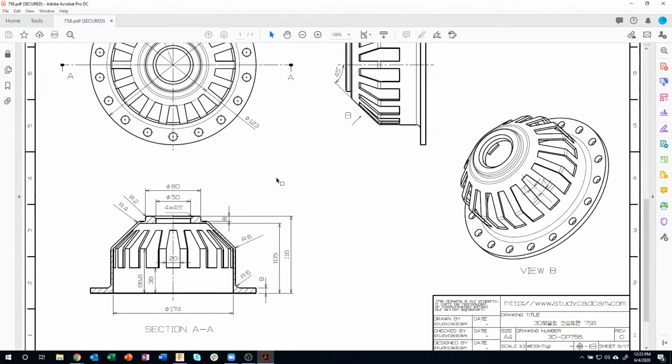Well, there's a couple options here. Now, I'm a little bit nervous because I said I want to shell this part out, but you'll notice that this foot here is a little bit thicker. I'm really kind of curious what's going to happen here. So we're going to have to figure out what's going to go on there. And it's also a little bit thicker up here. Now, when should I do this shell? And that's one of the questions you'll want to ask as you're parametrically designing this model.